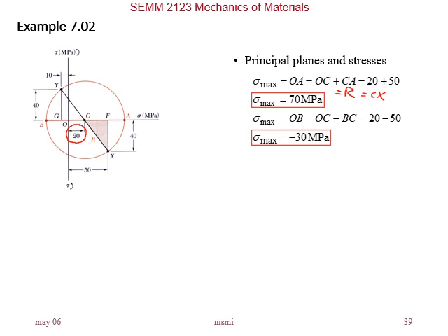Sigma minimum, this is a typo error. This should be minimum, not maximum. Okay, so that is sigma minimum. Right? Sigma minimum is equal to OB. This is O, and that is point B here. So it is from O, the centroid of the axis, where it intersects, that OB.